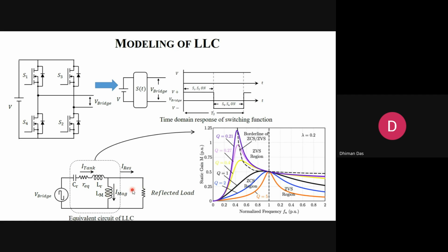You see, there is no other component, so it is acting like a potential divider kind of arrangement. Now this tank characteristic is shown here. For higher frequency you can have attenuation, but the attenuation and the gain characteristics depend on the load, which is also called the Q factor. Now when the load changes, your curve also changes. Your resonant curve keeps on changing and changing.